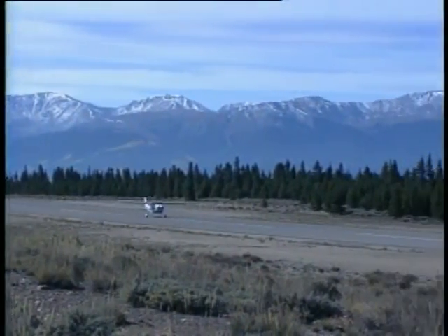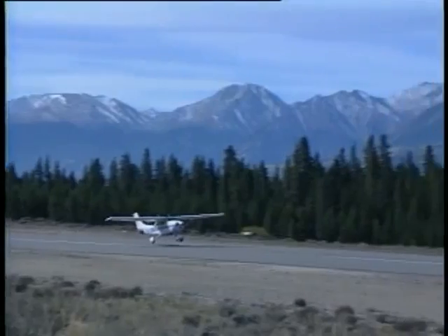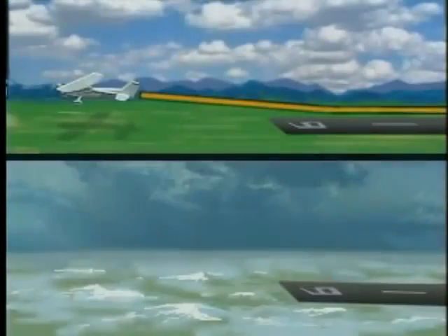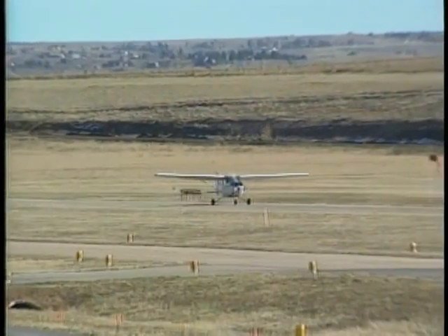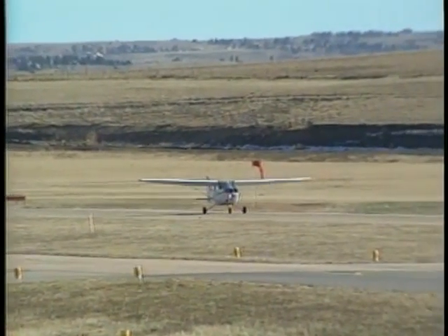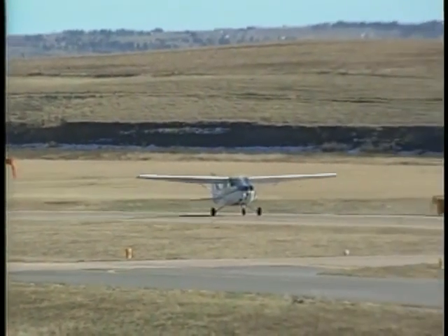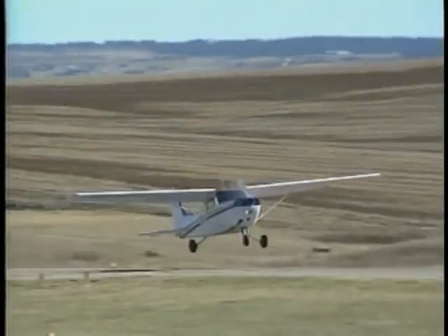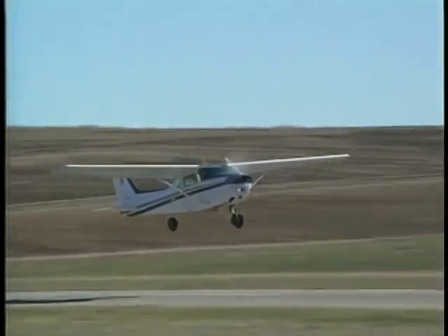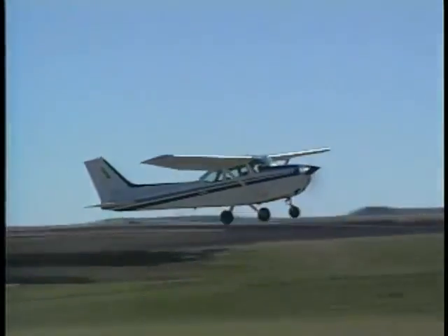Many times the focus is placed on the decrease of performance when training pilots transitioning from low elevation to high elevation airports. Don't forget that an increase in performance at lower elevations or cooler temperatures may also be unfamiliar to pilots if they are accustomed to flying at higher elevations. Calculating takeoff and landing distances may help reassure the pilot that what appears to be a very short runway is sufficient in length. Also, the pilot may not be aware of the increase in climb performance and have a tendency to overshoot the desired level-off altitude.